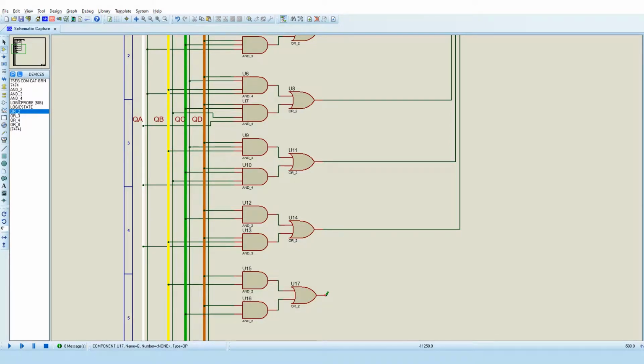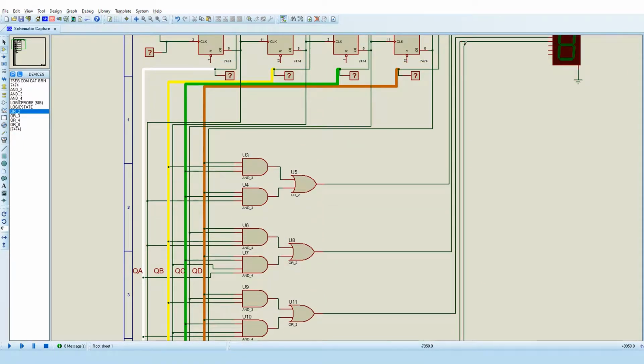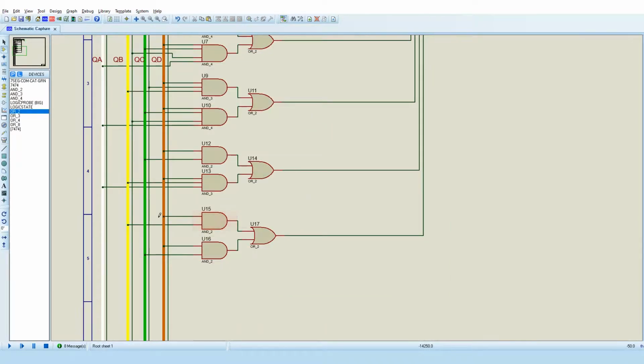So that's that. Wire the output to segment E, but we're also going to wire it to segment G because they have the same Boolean expression. So that's segment E. Then I take a wire from segment G, the last segment, and just connect to E. And then finally, segment F, which the expression is D and B, we've already made D and B for segments E and G. So what we can do is get a junction